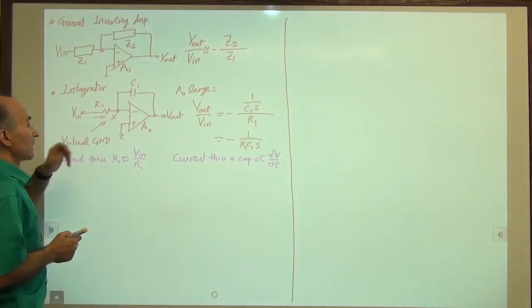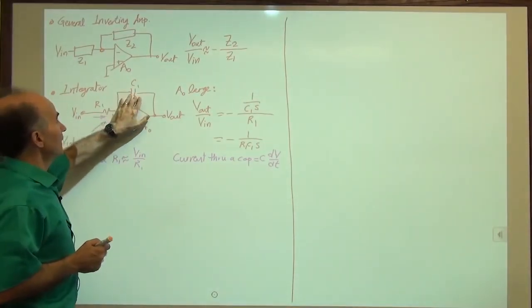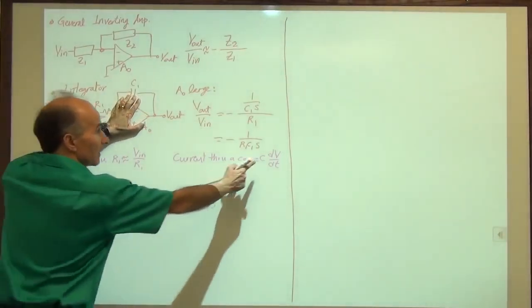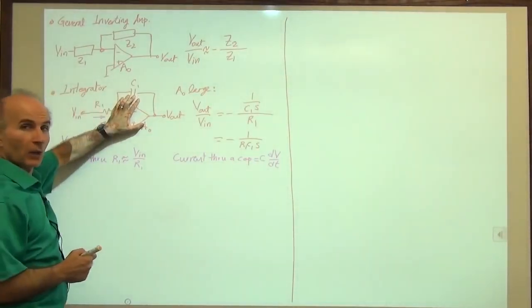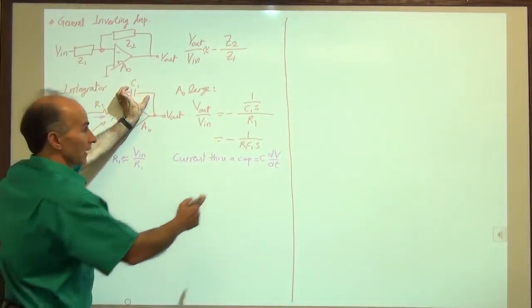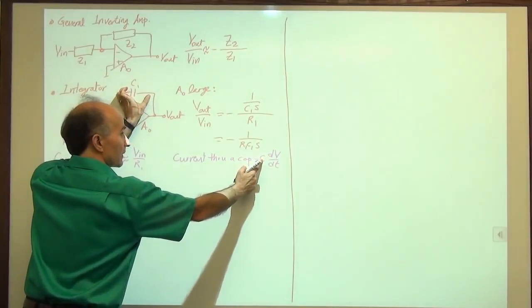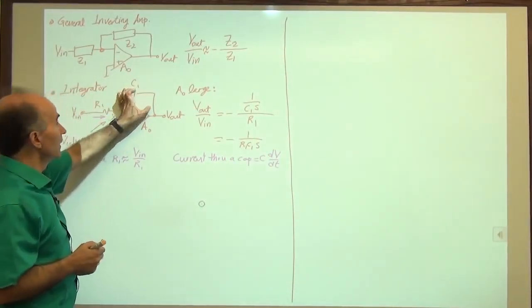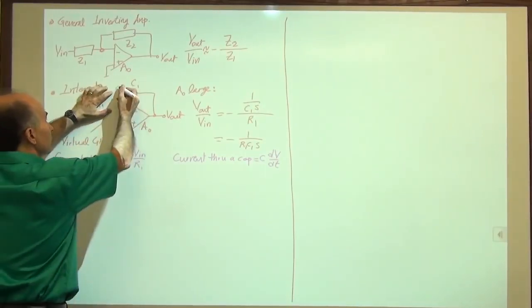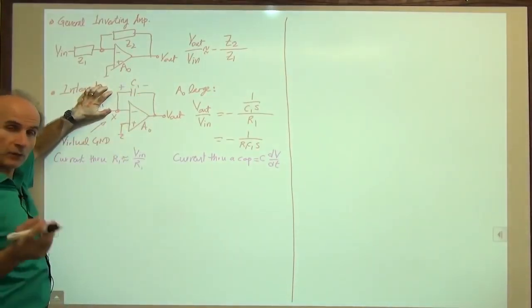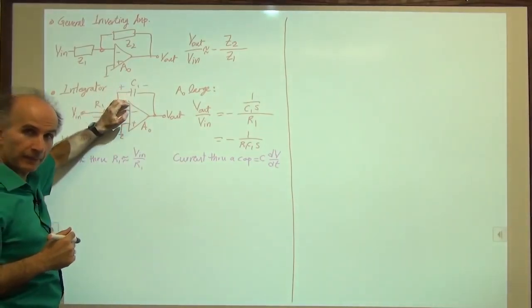All right. Now, can I write an equation for the current through the capacitor independently using this equation? Well, I can say that the voltage on the capacitor, derivative of that, times the value of the capacitor gives me the current. So let's try to do that. Let's assume that the voltage of the capacitor has positive on this side, negative on this side. It's up to you, but you can pick it like this.